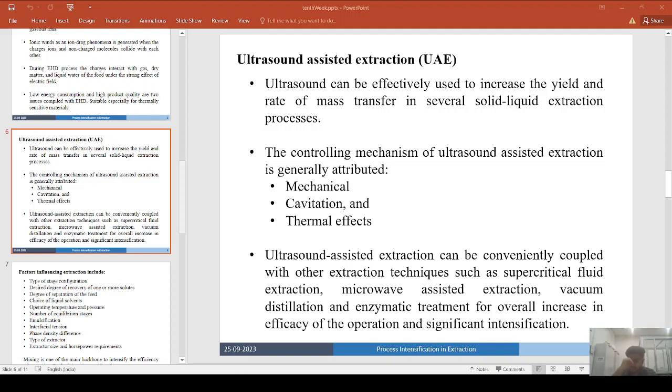All of these three, the microturbulence, high velocity interparticle collision, and perturbation in microporous particles of the biomass due to the implosion of cavitation bubbles, will accelerate the eddy diffusion and internal diffusion. It has been reported that microfractures appeared in the particles after the application of ultrasound, and the surface morphology of the particles changed, giving a more porous nature and enhancing the mass transfer of the extraction. For example, extraction of oil from soybean flakes, autoclaved almond powder, and extraction of ginger oils from ginger.